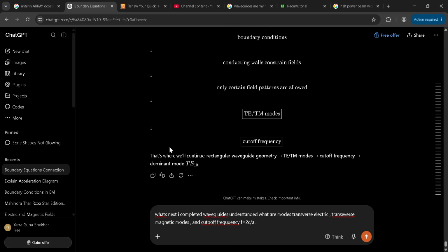So we got resistance, right? We got resistance, and we'll calculate between A and B. We calculate the voltages at the A node and B node using KVL. Then we take the difference and we get the A to B voltage drop, which is called V Thevenin. Then we need to calculate R Thevenin.